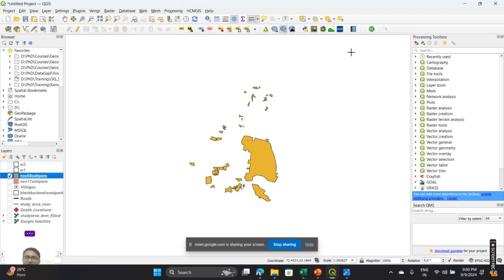What we learned in QGIS today is how to add different data, vector data and raster data. In vector, line, point and polygon data, how to change the symbology, color, visualization, labels, and then how to visualize raster data, how to set different color ramps, invert it, how to see minimum, maximum values, and then how to add CSV data sets as well.